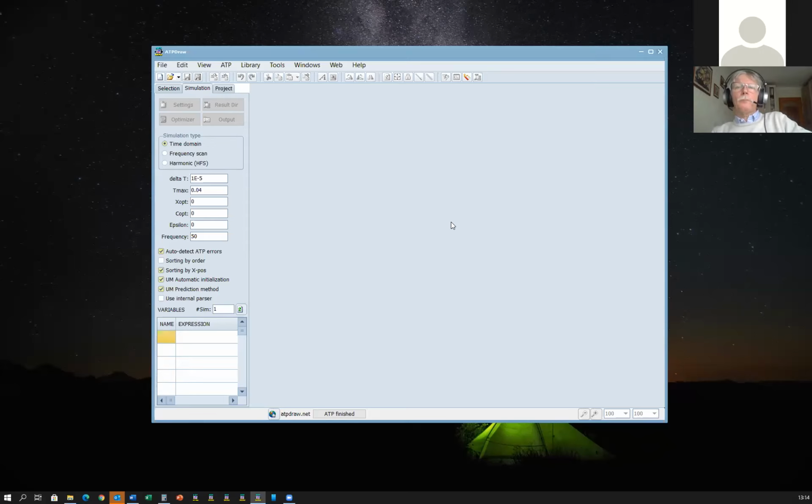Okay. Another one is for autotransformer modeling to model nonlinearities. Is XFRM the most suitable model? You can also use BCTRAN.